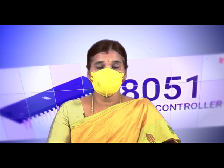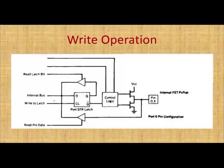In port 0, how are we writing the data? Writing the data means we are sending the data from the bus to the external pin, in this direction. So this is the address and data signal, right, and this is the control signal. Now the control signal is 0, so this transistor is going off. Now you are planning to write, and at that time the read pin and control are both in the 0 state.